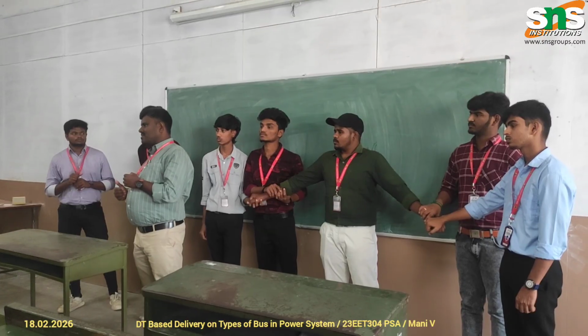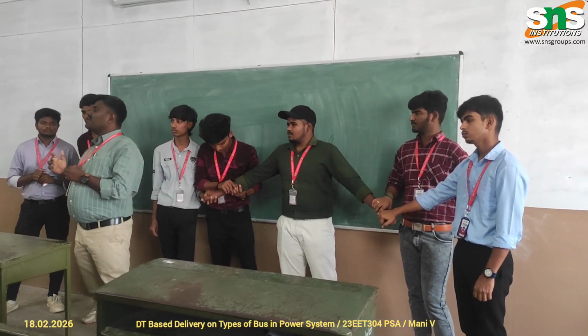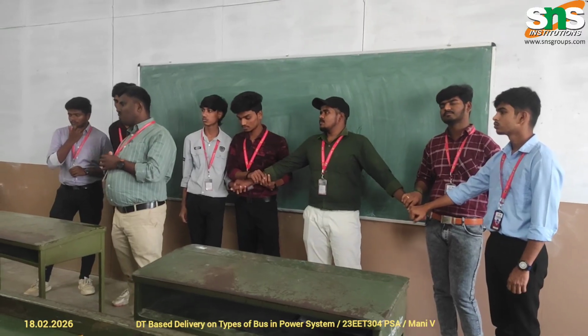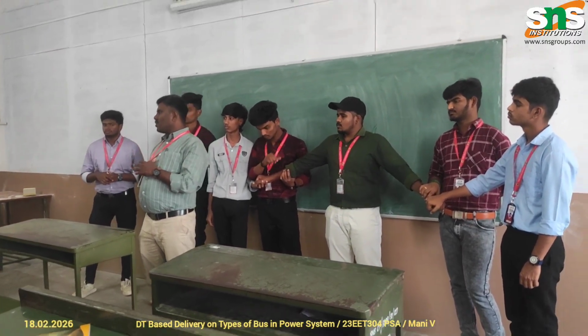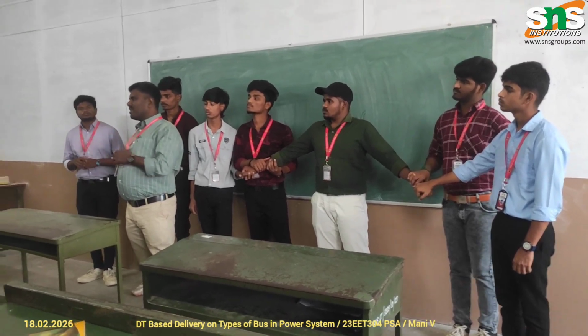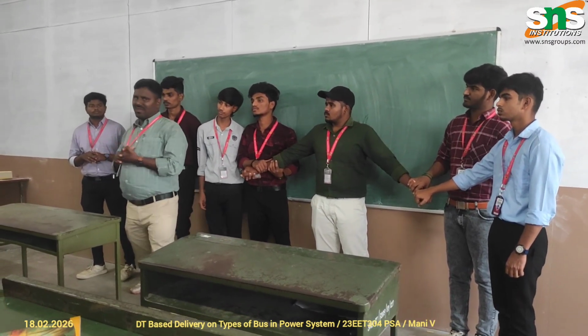In each bus, out of the four quantities, only two are known, and the remaining two are unknown values. We have to determine them using either the Gauss-Seidel or Newton-Raphson method. These are iterative methods. So we will see how the buses can be classified.